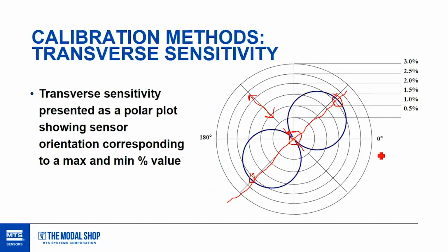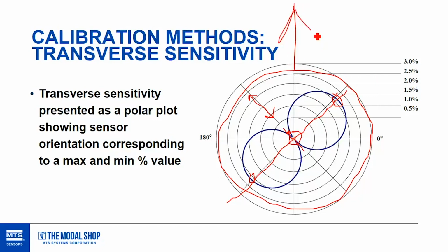And that shaker, if you can imagine this outer circle here is the top of that shaker, physically that shaker is going to have some vector, some direction in the XY that is going to be the dominant rocking mode for that shaker. So it's going to be perhaps rocking in this direction. So you'll have a ton of motion, in this case up and down, on the shaker head as it's vibrating.